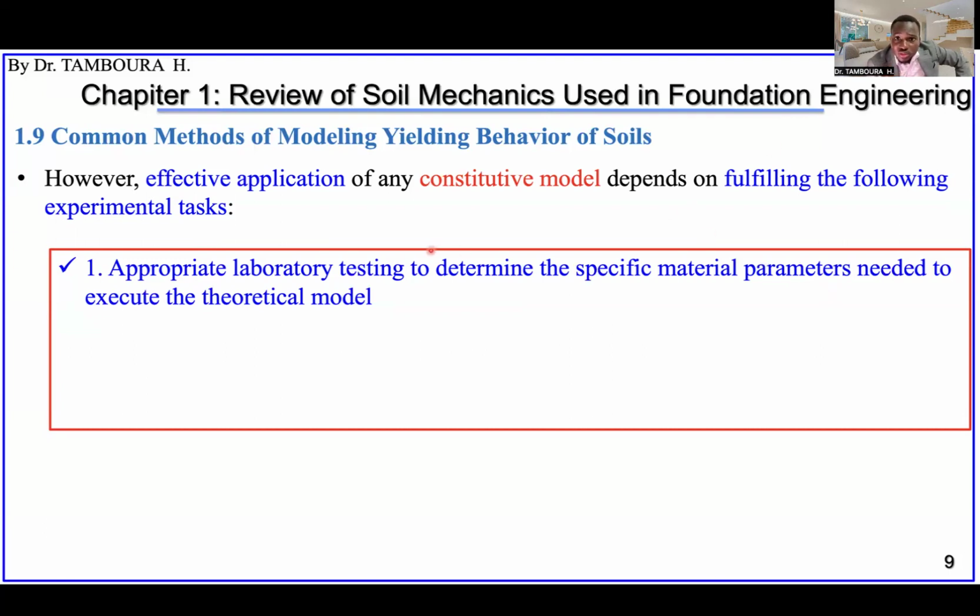The input data, you have to know them. No model will give you the parameters. So you go to your construction site, you take soil samples, and you go in the lab and do testing, and you get the soil parameters. The soil parameters will be your input data.